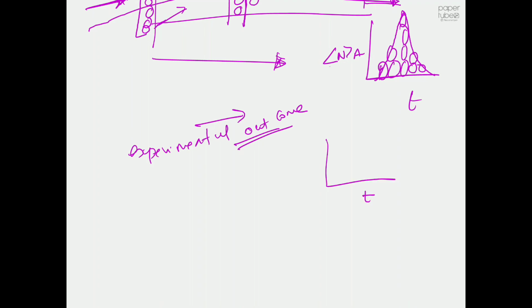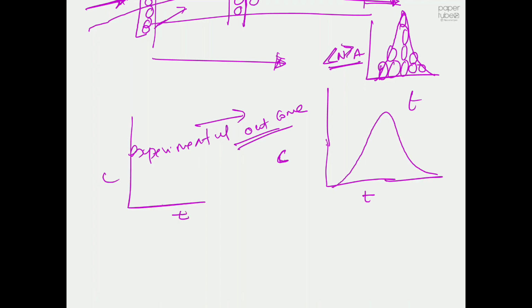Here I just put number of molecules only to explain the concept, so just put concentration here. So we will have a Gaussian distribution. No matter what, even if you place a concentrated plug at the column inlet, when it exits the column, you will have a Gaussian distribution.